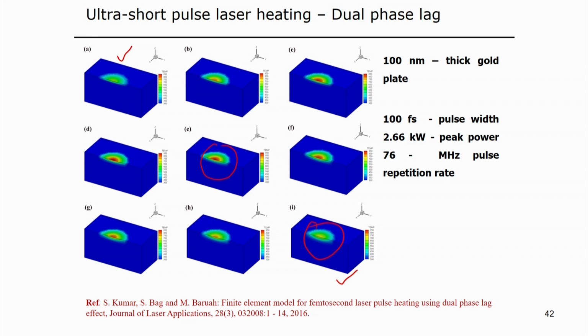That means this simulation signifies that with the application of the flux on the surface, there is a movement in the development of the temperature distribution that actually defines the penetration. There is some relaxation that exists. That means with the application of the heat flux, it is not instantaneously developing the temperature distribution to a certain depth. So, some time lag is required, some time lag exists, and that is obvious from all these simulated results.